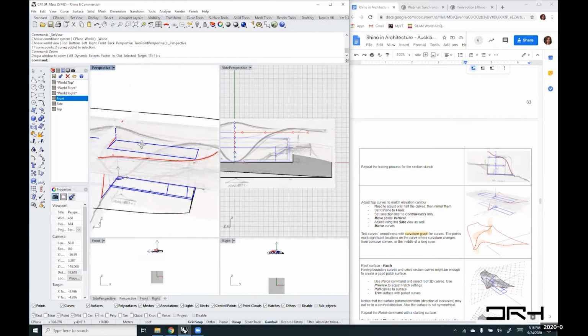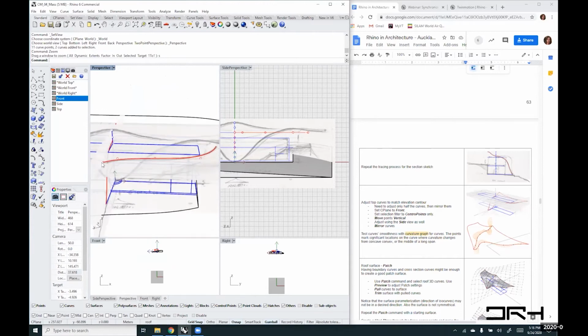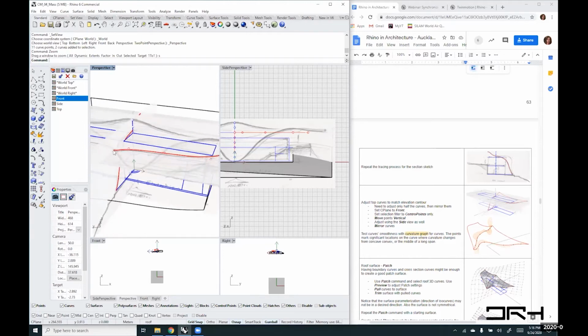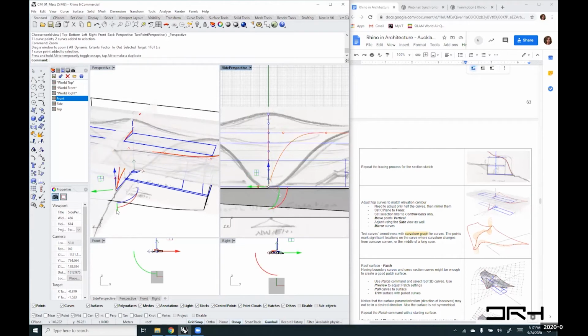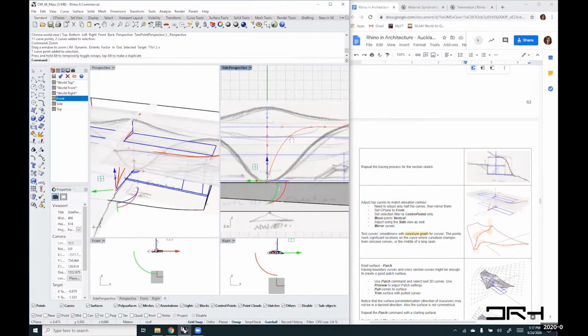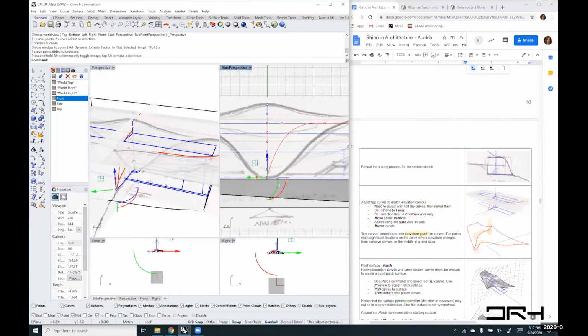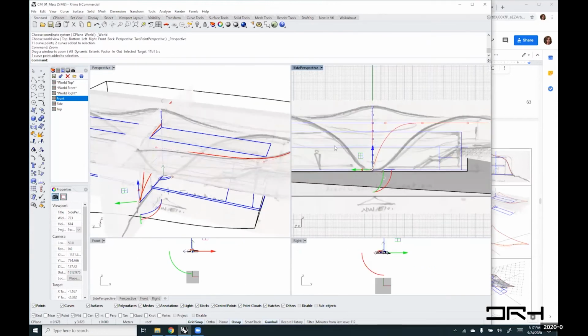And so now if I need to move that tip point, I can select it in the perspective view here, but I can move it in the front view, because I can more easily move it vertically using the arrows here in the gumball, as you can see, and I can snap it all the way down here, right? So I can see it better here. Let me just make this a little wider as well.